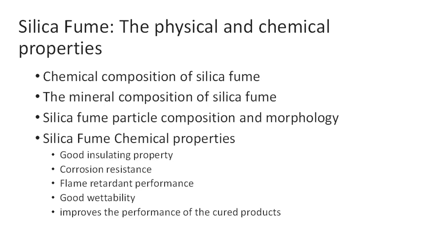So now let's focus on silica fume. The chemical composition of silica fume is quite simple, with 85 to 96% of it being SiO2, primarily in amorphous form. This high content of amorphous silica is the key factor behind its effectiveness, and it is often compared to volcanic ash in terms of properties.